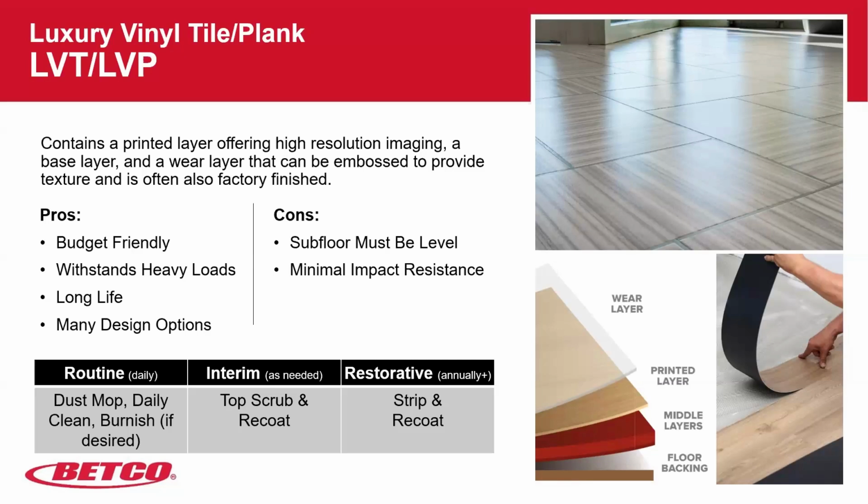That's the wear layer. Underneath that wear layer is that printed layer. That's where you get your vibrant colors, you get your pictures, your logos, all that stuff in that printed layer. Once you wear through that wear layer, you're into that printed layer, and that's where the floor starts uglying out, and that's where you get soil embedment, you get liquids and fluids building, staining underneath that wear layer. So that's where the maintenance of LVT, LVP is very, very important.